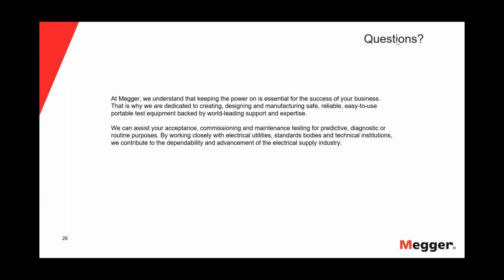Thank you, Henning. Javier, are there any standard specs that I can incorporate into my project specs? Yes, of course. For instance, for acceptance or maintenance tests, we can use the IEEE 400.2. Also for tan delta applies that standard. For partial discharge, we can use the IEEE 400.3 and 400.4.